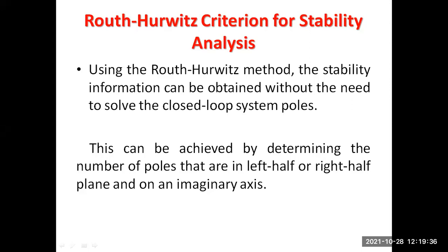But this practice was not found good, since it is not always true that if you plot in the s-plane and the roots lie on the left half of the s-plane, the system will be stable. This statement is also not true. So in that case, what has to be done? Routh and Hurwitz developed this stability criterion, and with its help we can determine stability very easily. We'll understand this in detail.